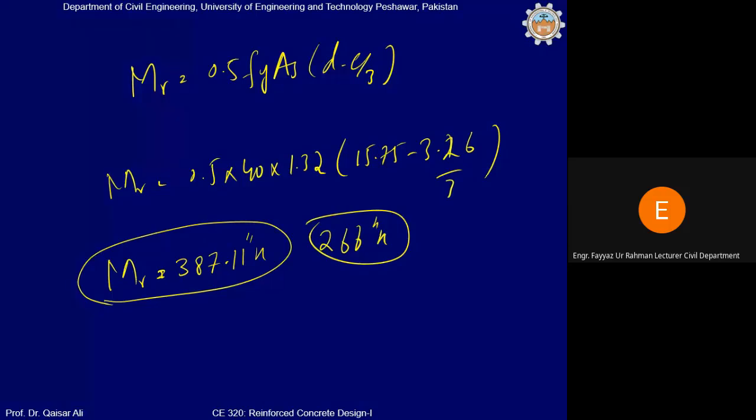See in the beam video also, at 30 kilonewton there was the first crack, and the number of cracks increased and the load value also increased. At this stage the load value was almost 50 kilonewton. Is this clear? Yes sir, yes sir.